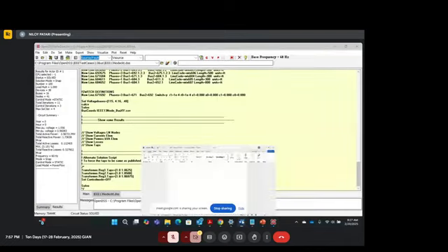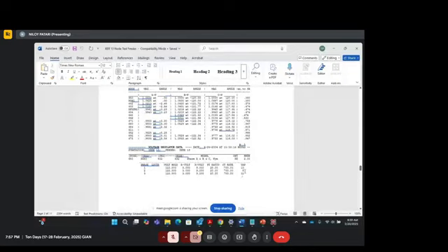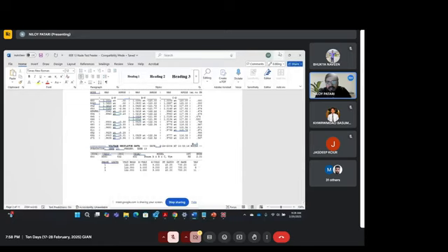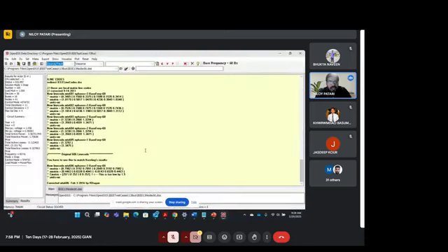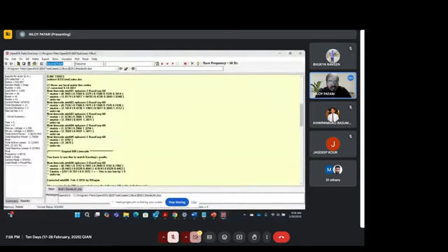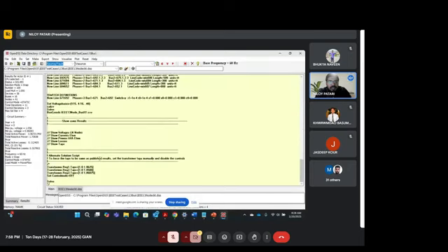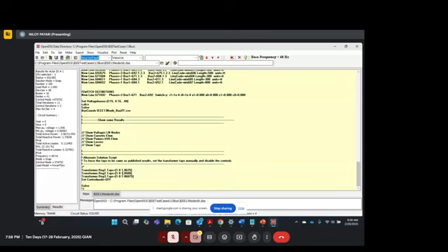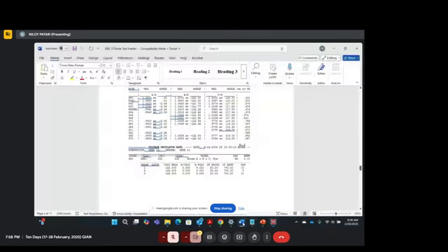So now you see the voltage regulator setting in the manual is 10, 8, and 11. If you multiply 10 with 0.00625, it will come up to be like that. So here the tap goes from 1 to 1.0625. What was the next one? It was 8, right?